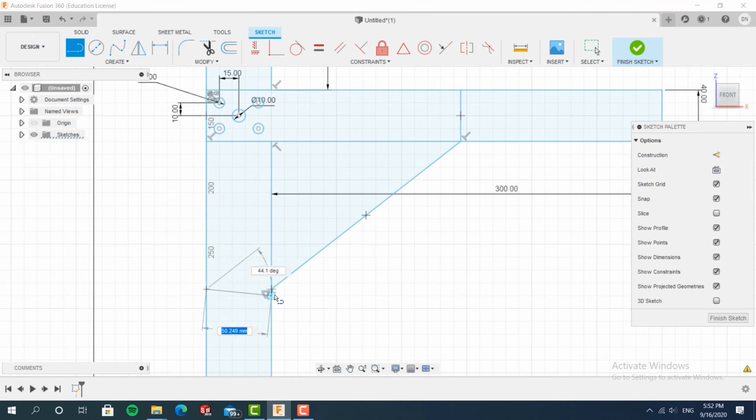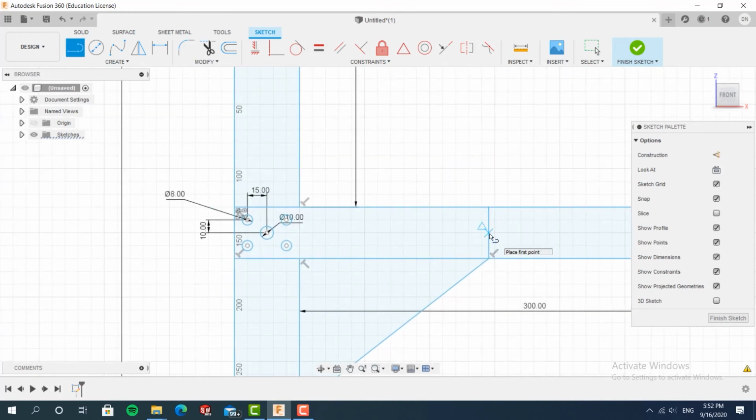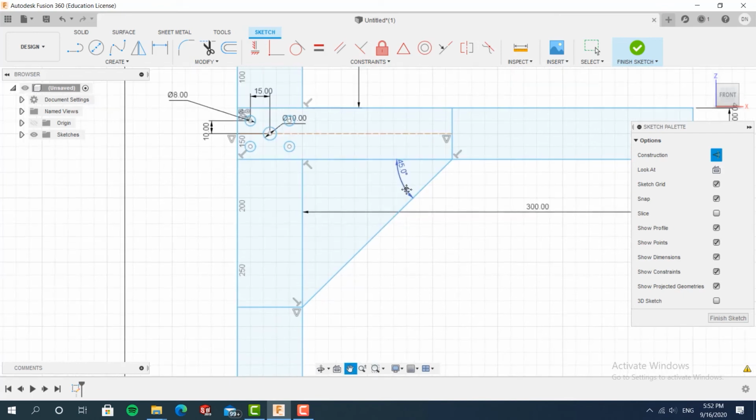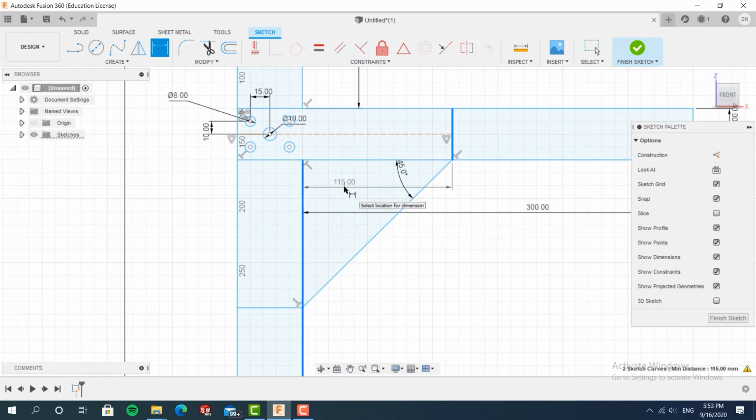Also, support parts that are going to be directly attached to some spinning axles because they are going to move around a whole lot. There's going to be a lot of backlash. They will get loose very easily from constant movement, so please support them. Another thing that you need to support is parts that are overhanging a bit too much. Basically, just count the number of parts in between that thing and your base. If it's larger than the numbers of every other part, probably it will need support.